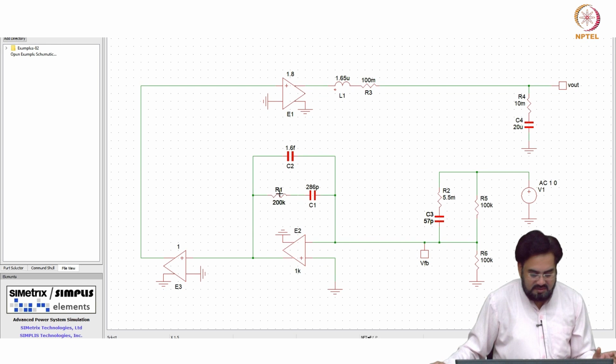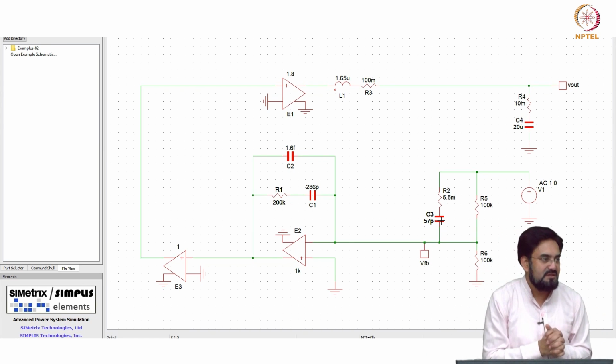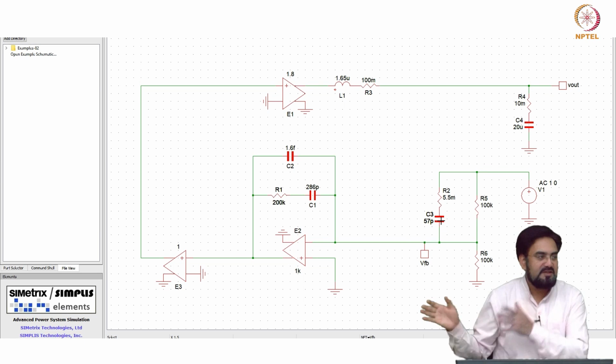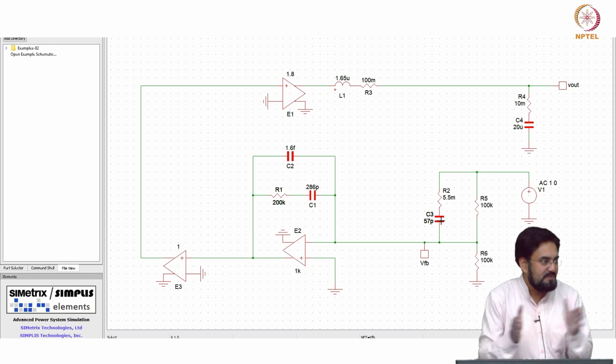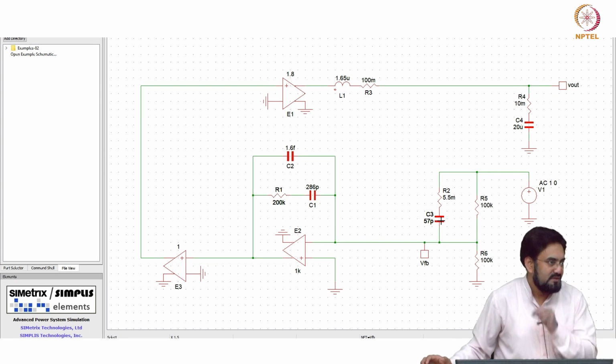And the same thing, if you move the second 0 to a lower frequency, your phase will be boosted, because then the phase contribution by this 0 at UGB will be more, because the separation between your UGB and that 0 is more. So that will add more phase at UGB.